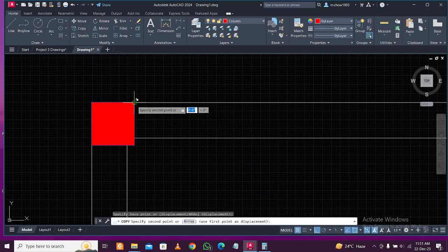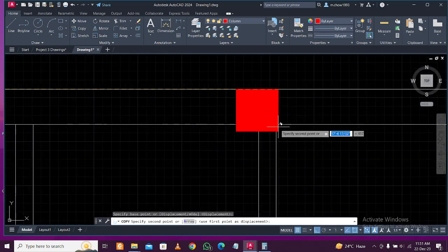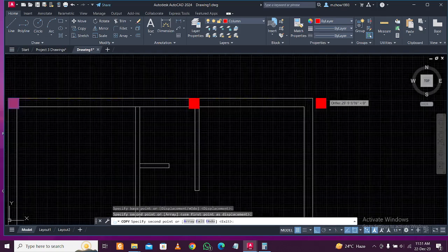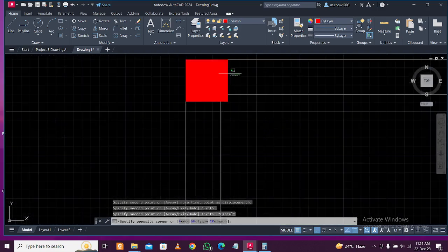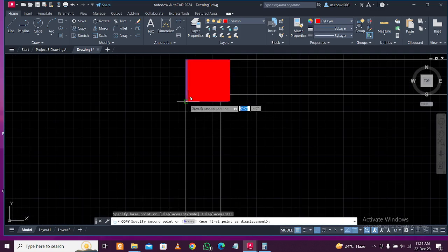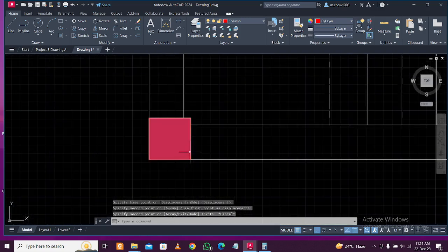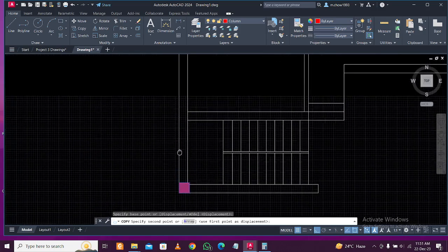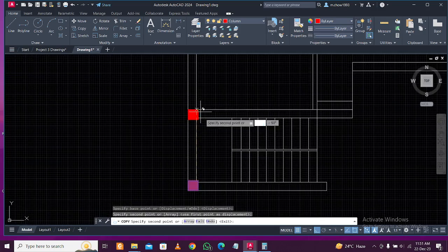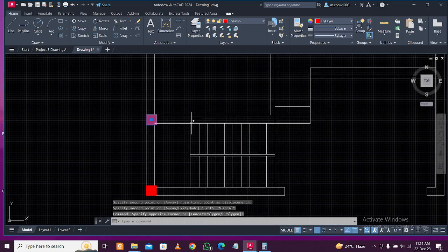and then another column will place it along this and along the end. So let's do the staircase also. Columns, pretty obvious things you do first in a plan, and then you decide for the more complicated ones. Okay, no problem in that, because for a staircase obviously you need 4 columns for the headroom, so there is no doubt in that. So finish that portion first,